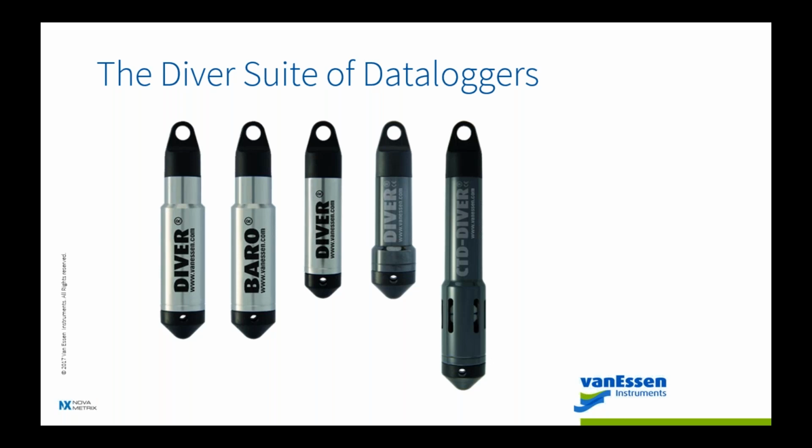This unit is very cost effective for the quality it's putting out, and this is a real workhorse as far as data loggers go. This diver, you set the fixed rate. That's the only choice you have with this unit. Although you do have very fast sample rates that you can do with it. But this unit is set it, fixed rate, and then go till it's full, or you need the data from it, and you pull it. You can re-zero it by stopping the diver and restarting it. So the TD is the long-term monitoring solution.